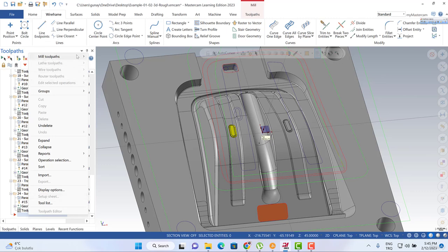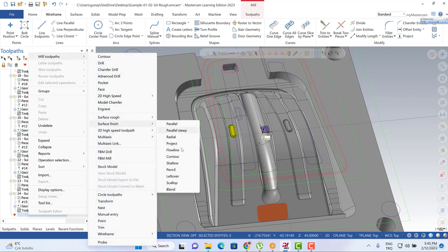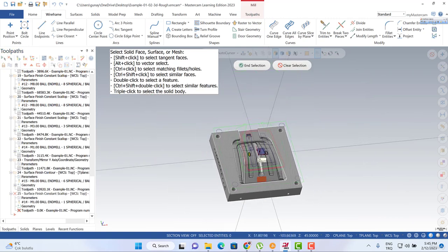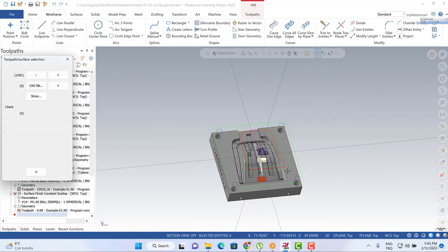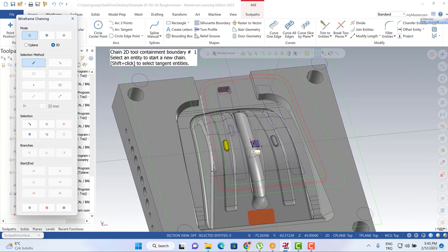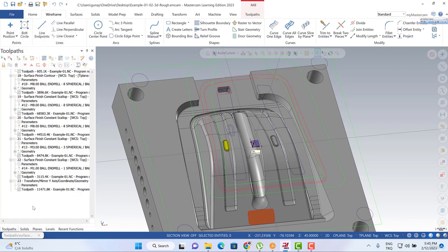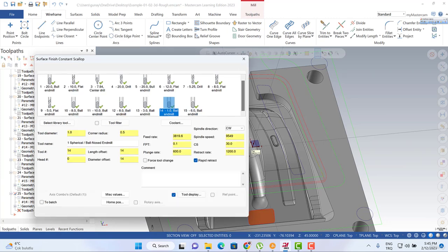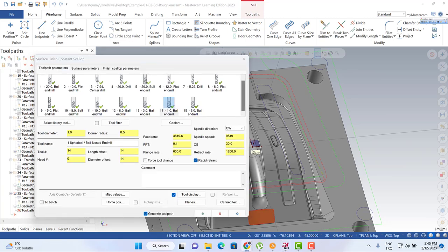Let me turn back to here, mirror toolpath and surface finish toolpath and the scallop toolpath. And when we select the scallop toolpath, it's also possible to focus on the leader area, of course, but that's not so important because there are no more faces to expand our cutting time. So that's why I'm selecting all the faces.